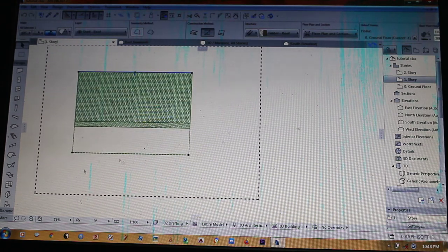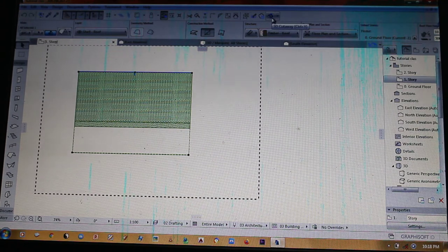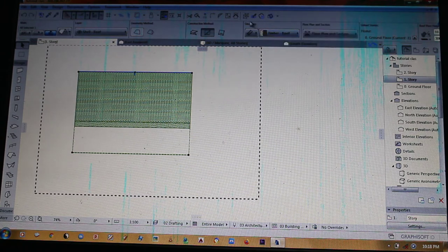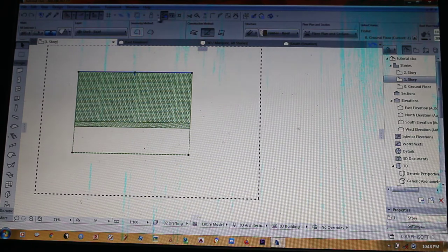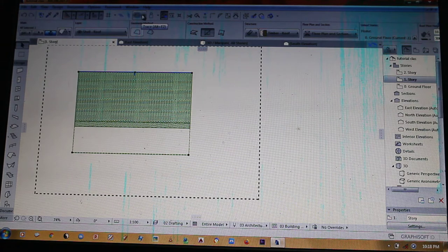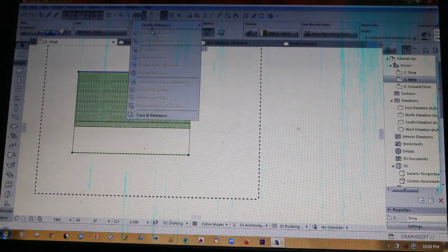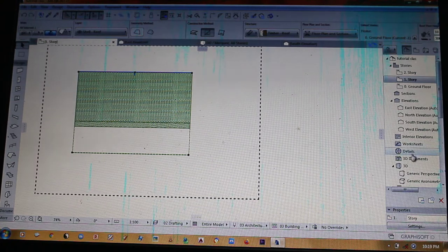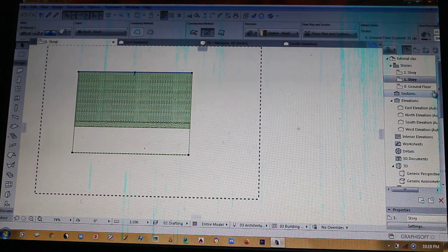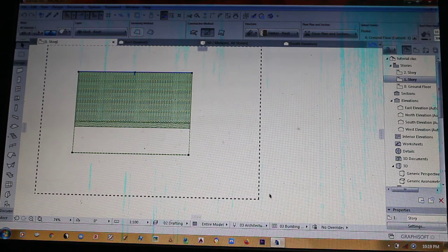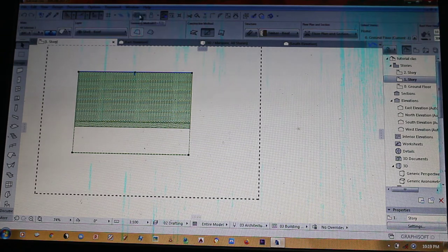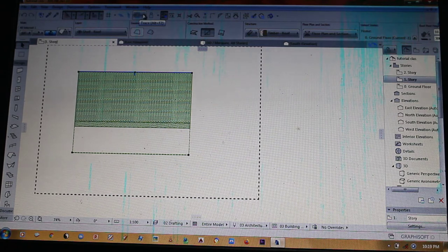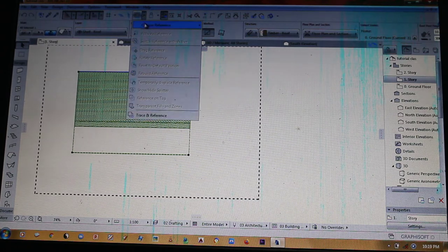And then we have to make sure that we have a reference to the lower part so that we can clearly see what is going on. When we are on the first floor, we have to see what is on the ground floor. So we have to set that reference. What we do, we come to this element trace, then we click on this pointing lower arrow, and then we choose a reference.